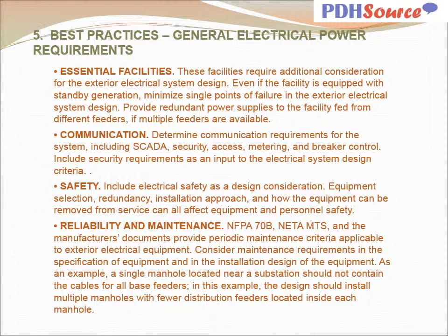With regard to communications, determine communication requirements for the system, including SCADA, security, access, metering, and breaker control. Include security requirements as an input to the electrical system design. Include electrical safety as a design consideration.